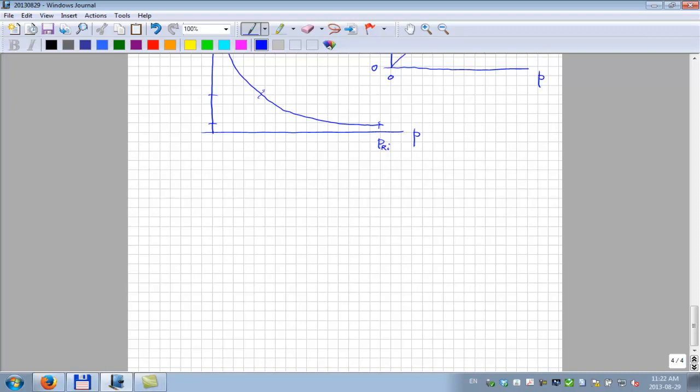So the next application of this equation, and probably the most important one, of the ideal gas law, is to give a means to convert standard volumes or surface volumes to moles, or from moles to surface volume, surface gas volumes. That translation from moles to surface gas volumes back and forth goes on all the time in different engineering applications.